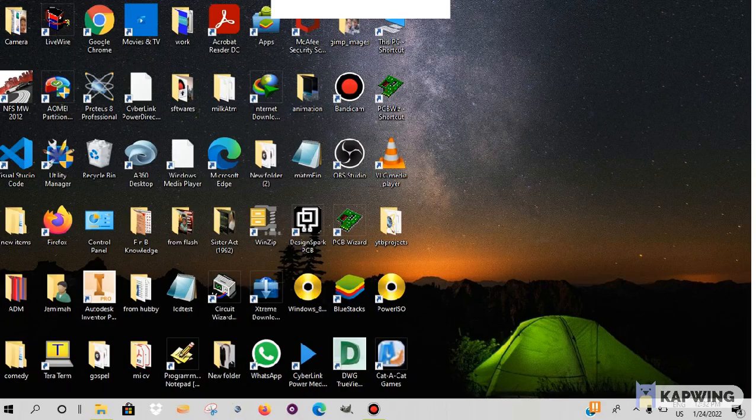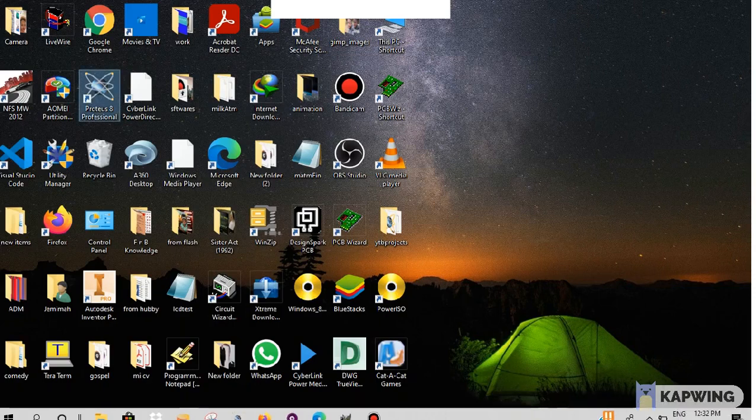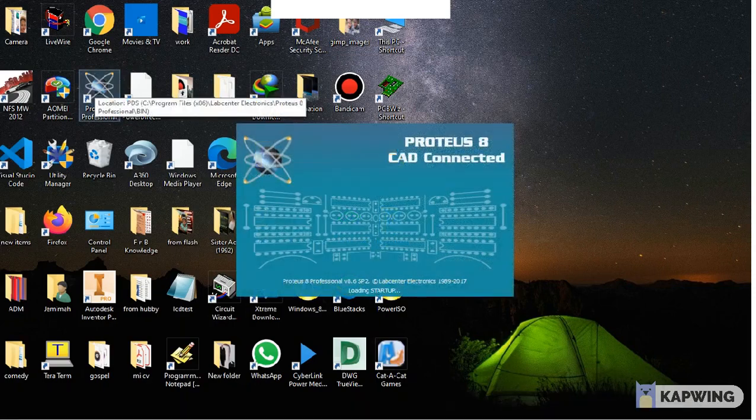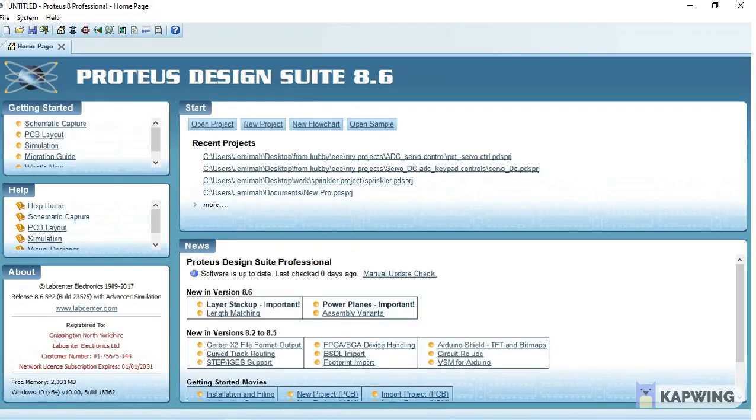For us to do that, we'll need two of the tools that we talked about in the earlier videos. This is going to be this tool over here, Proteus. Just going to open it, and WinAVR, because we'll need it as a compiler. We are actually going to do it in a virtual environment, and then later on we'll do it with physical hardware, the real atmega32 chip. But for today, everything is going to be done in a virtual environment with virtual hardware.